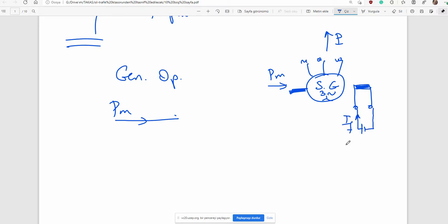So here we apply some field current, DC current, to the rotor main field coil, and some magnetic field is produced in the rotor. When you rotate the rotor, that magnetic field rotates around the stator slots and induces electromotive force in 3-phase, if you have a properly arranged 3-phase winding in the armature.